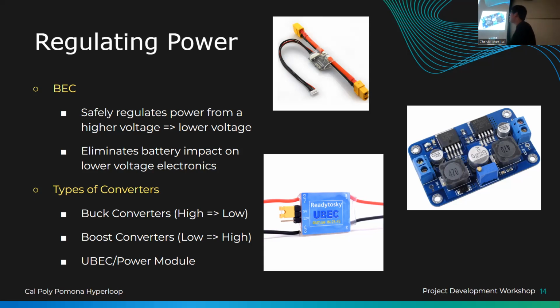This one combines both the buck and boost converters and allows you to either scale the battery up or down depending on this potentiometer. Either way, though, you also have to be considerate of the amount of current you draw from the batteries, and of the amount of current that this module can hold. This one, I think, is a 3 amp limit, so if you want to draw any amount of current over 3 amps, you either have to put these in parallel or get a better buck converter or a transformer.